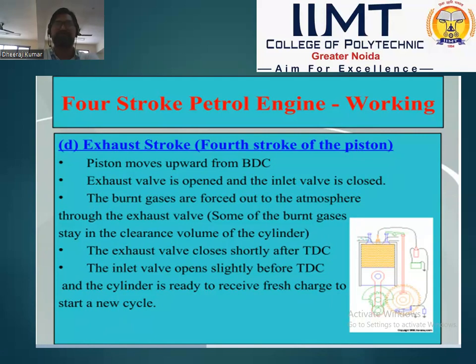The inlet valve opens slightly before TDC, and the cylinder is ready to receive a fresh charge to start a new cycle. During the exhaust stroke, the piston starts at BDC and moves from BDC to TDC. During this stroke, the inlet valve is closed and the exhaust valve is open, and hot gases move out through the exhaust valve. When the piston reaches TDC, the inlet valve is partially open and the fresh air-fuel mixture comes inside the cylinder.